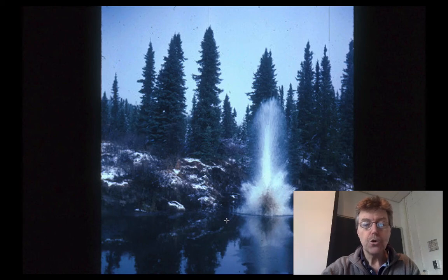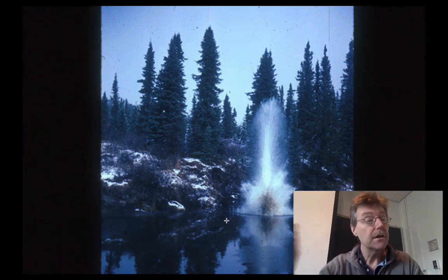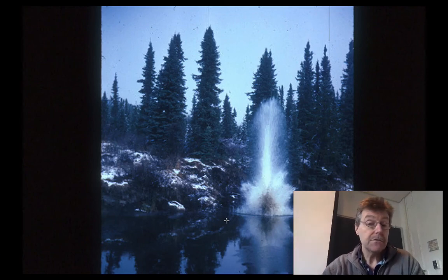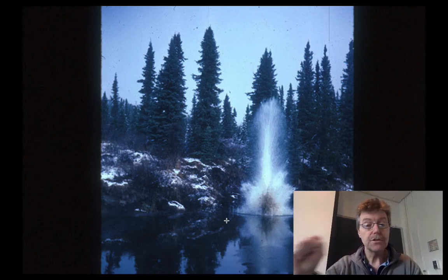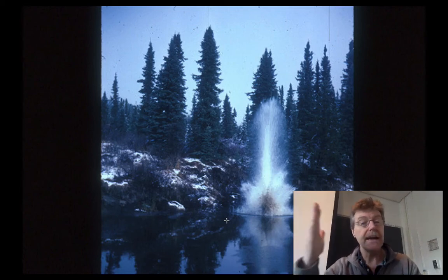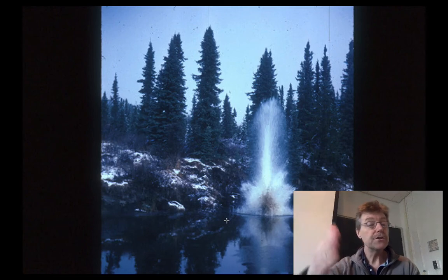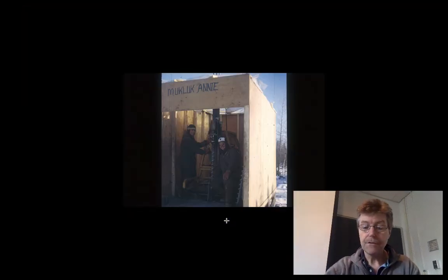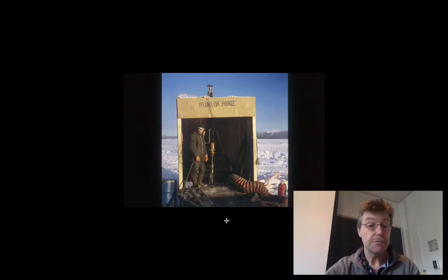And you use a quarter stick of dynamite to either put in the ground or to put in the water and trigger with a blasting cap to give the seismic impulse, which is the source that you'll read. So you trigger it, you know the exact time that it's triggered because you've given it the electrical pulse, and then you measure the first arrivals of the seismic waves as they arrive at the instrument.